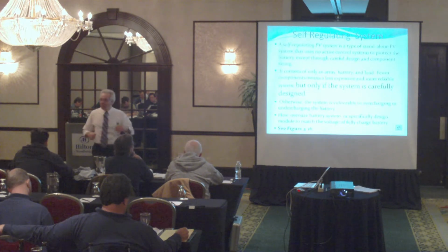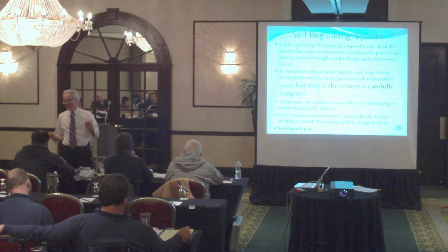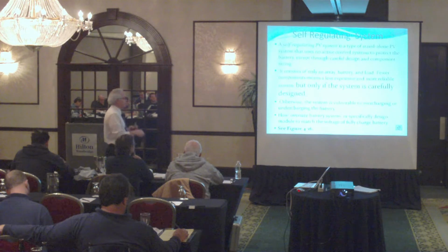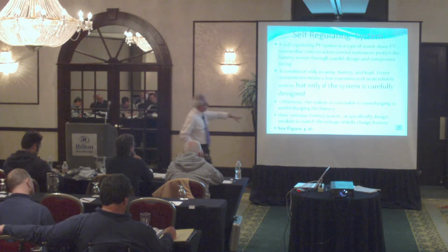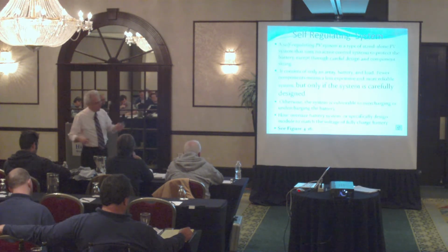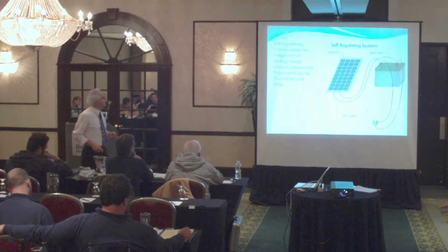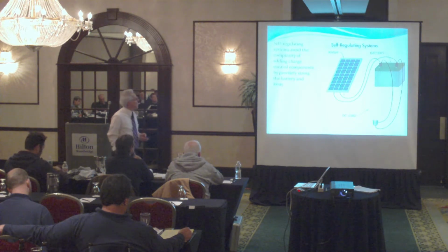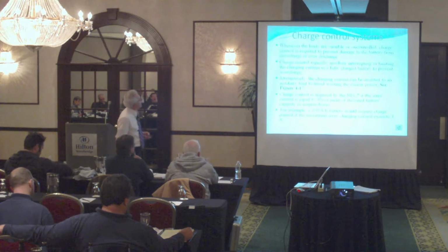So usually what you do here is oversize the battery should you have a condition like that. Otherwise you overcharge the battery, or you really are matching the voltage to a fully charged battery. So this is the only consideration. Most of the time, if you have a system like that, you oversize the battery, and then you're pretty good at it. Not that you're going to get involved with these things, but it's nice to know. This is what we call self-regulating, with the only components that you have in here. If you don't, then you can kiss the battery goodbye.